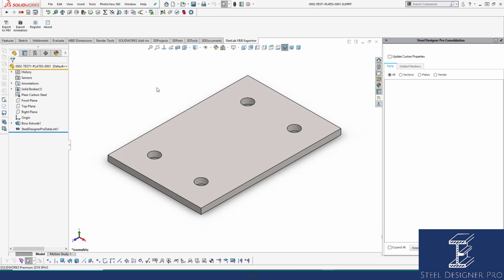Now plates are a bit different again. They are just an extruded boss. They can even be a mirrored component, but consider that the mirrored components must have the same file name. So if you do mirror things, just be wary that the file name must match if you mirror. That means you may mirror into a component, but you need to rename the component to something that works like that. I don't suggest you mirror, but if you can't avoid it, mirroring can be quite an interesting process.